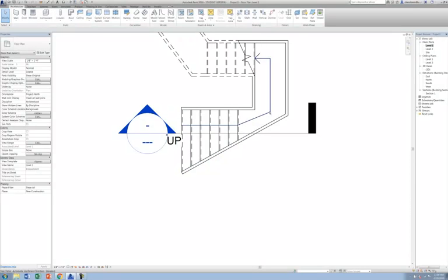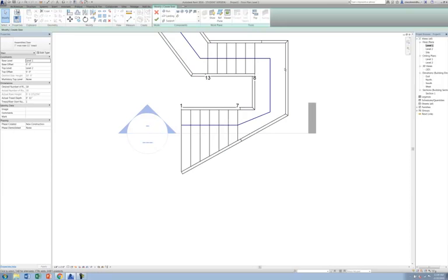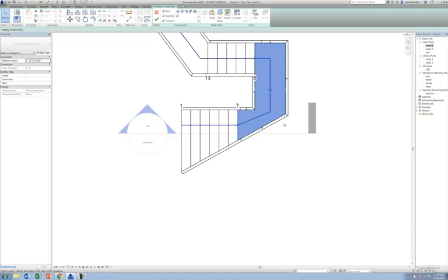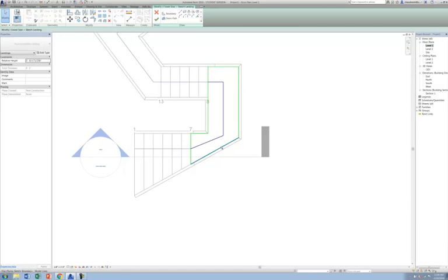So we can hit the checkbox here, and again I can come back in, hit edit stairs, and this time maybe we'll edit this landing to make it legal and to play with the geometry a little bit. I'll convert the landing just as I did the first chunk of the stair and hit edit sketch. Again, I can grab components and pull them out. So let's say we put a little kink in this, and then maybe I'll use the start end arc to create a bit of a landing that might be overlooking a part of the project.